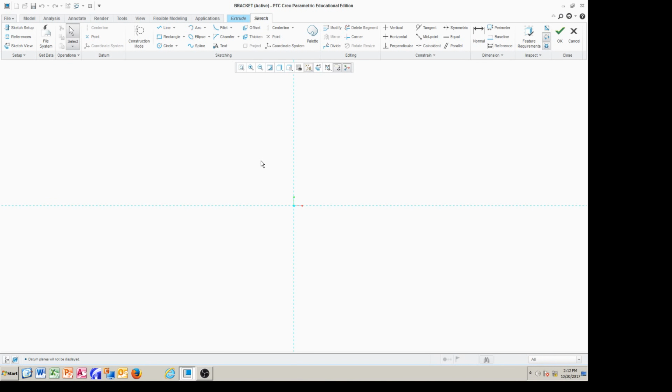If your sketch is not fully defined, then your solid model is going to collapse, especially when you're trying to do assembly. Okay, so this project is going to take us from creating the solid models, a total of 8 parts, and then having all the solid models saved in a folder that, as I mentioned in class, if you create a folder called Project1, you can call it shock assembly, and the shock assembly project.